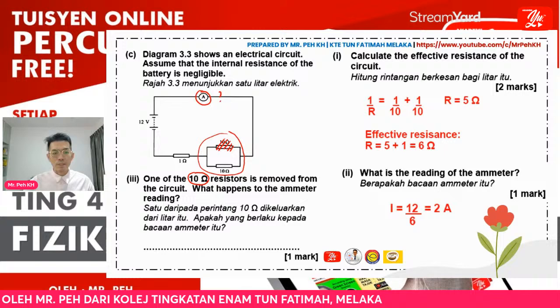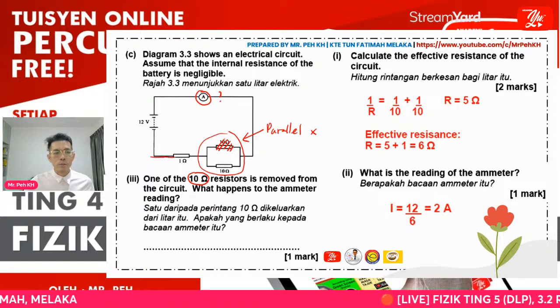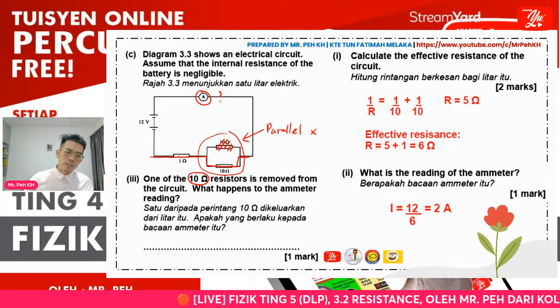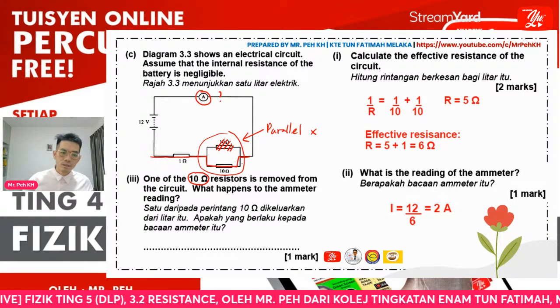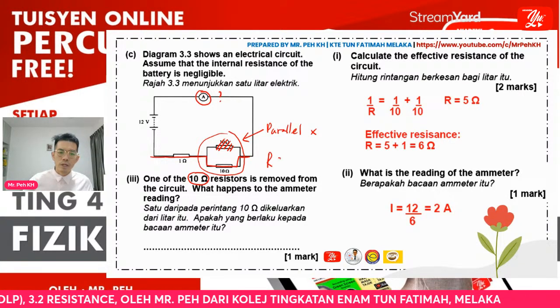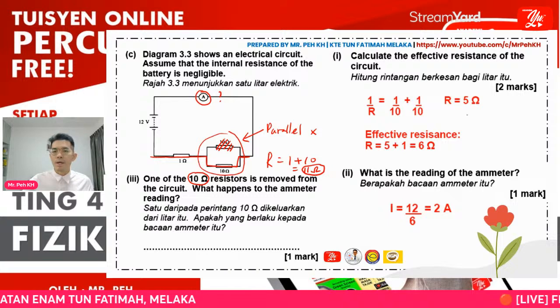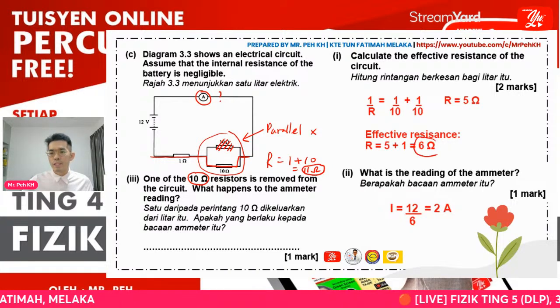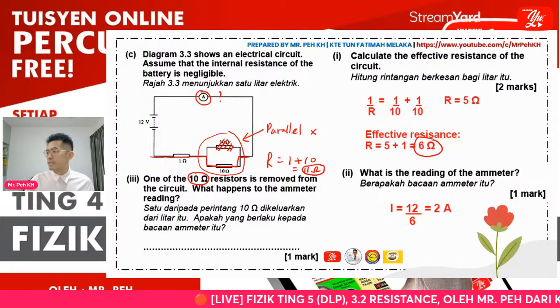One of them is removed, so that means you can see the parallel circuit is no more, and now there will only be a series circuit. Let's say you calculate the effective resistance in the current circuit: 1 plus 10, so there will be 11 ohms. Compare with the answer from number 1, which is 6 ohms. You may see that the resistance value has increased.